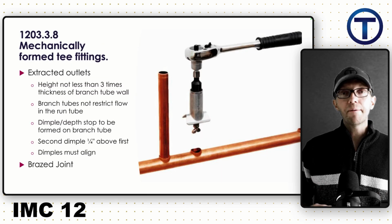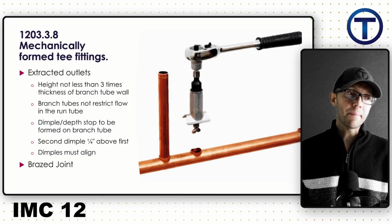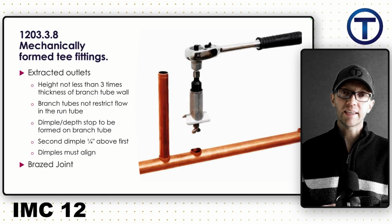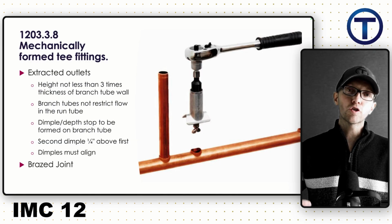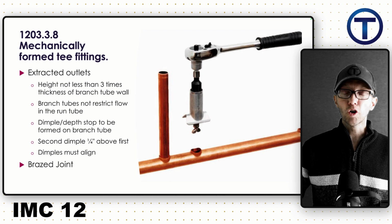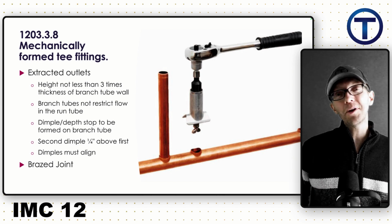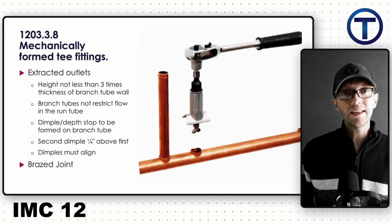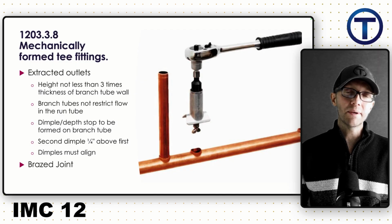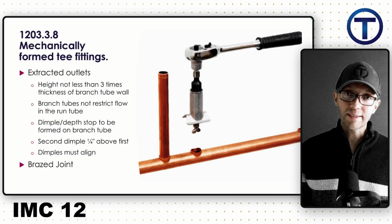There is another type of mechanical joint that can be used before soldering. This is a mechanically formed T-fitting. Another description for this is an extracted T, where you're not actually cutting into the pipe and installing a T, you're creating a T from the wall of the pipe itself. This, if you ask me, is almost outdated. Not many people are using this method because there are other methods, like press connect.